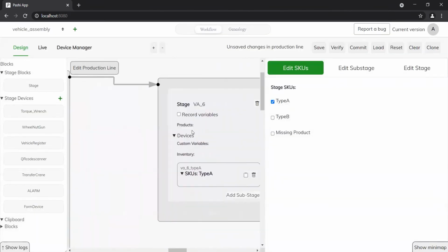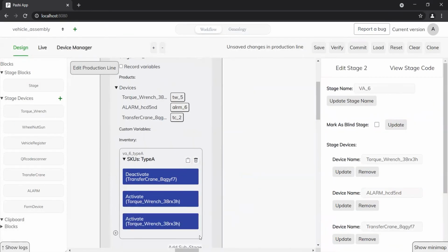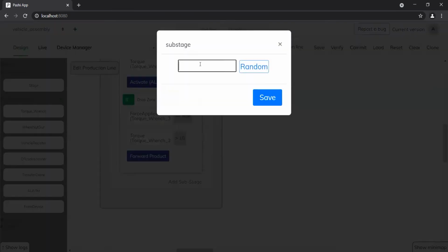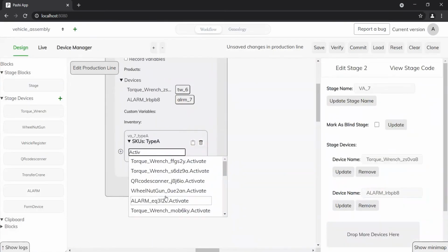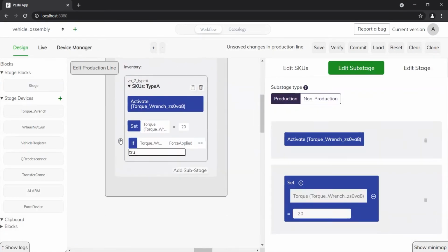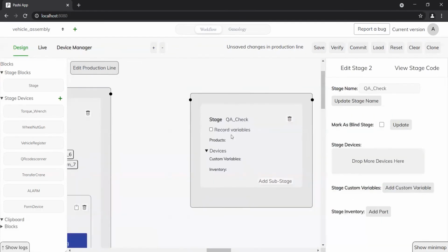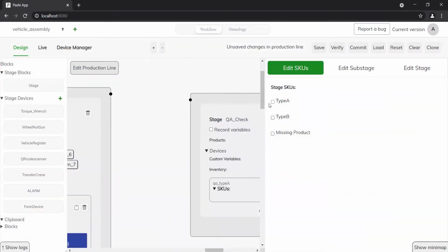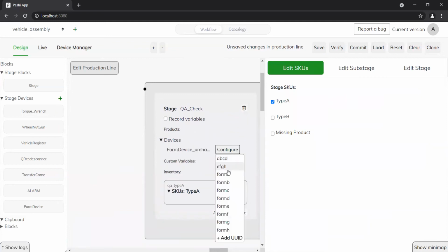The last few assembly stages involve the attachment of the rest of the interior and exterior panels, headlights, speedometer, seat, and pillion handle. While most of these operations are completely tool-free, we can still enable Poke-OK logic for the ones that use torque wrenches. Once the assembly is complete, the vehicle goes to the QA stage where operators visually check the vehicle for surface defects and panel gaps before sending it for the road test.